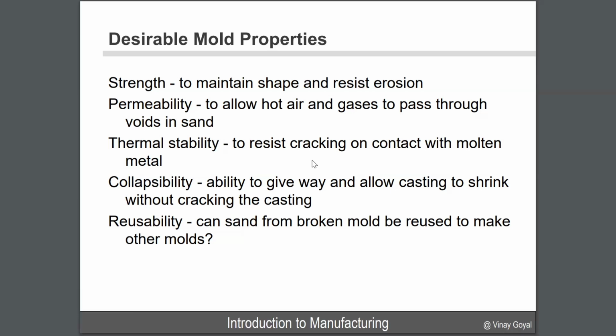The ability of allowing the casting to shrink without causing the casting to crack is instrumental. Why? If the casting cracks, that imprint will be on your part, and you don't want that situation. You are also looking at the bottom here when it comes to reusing that cast again. That's another one that should be thought about.